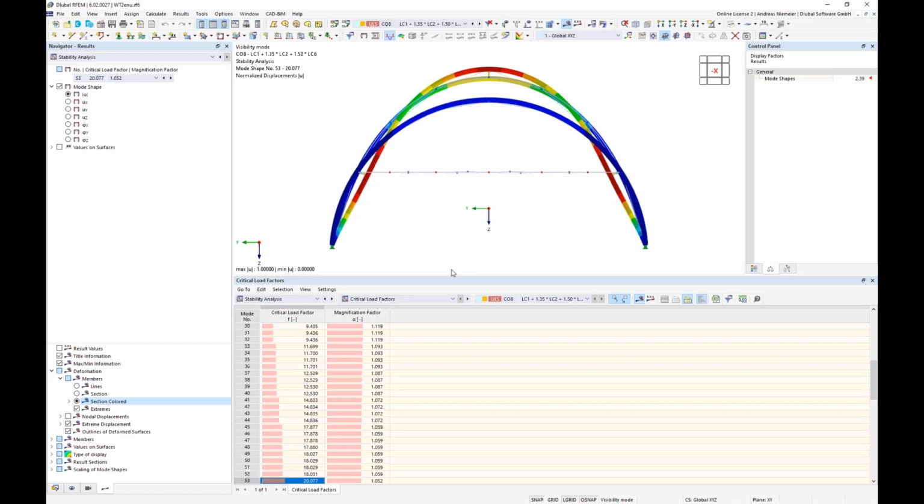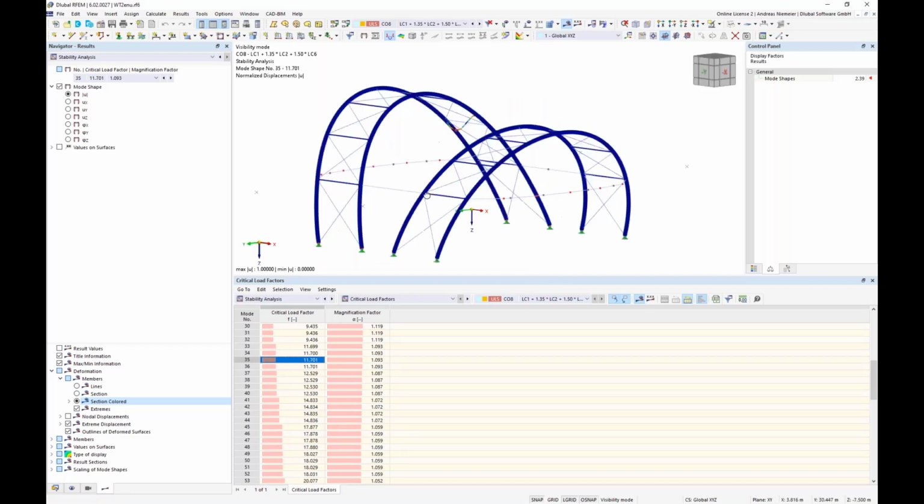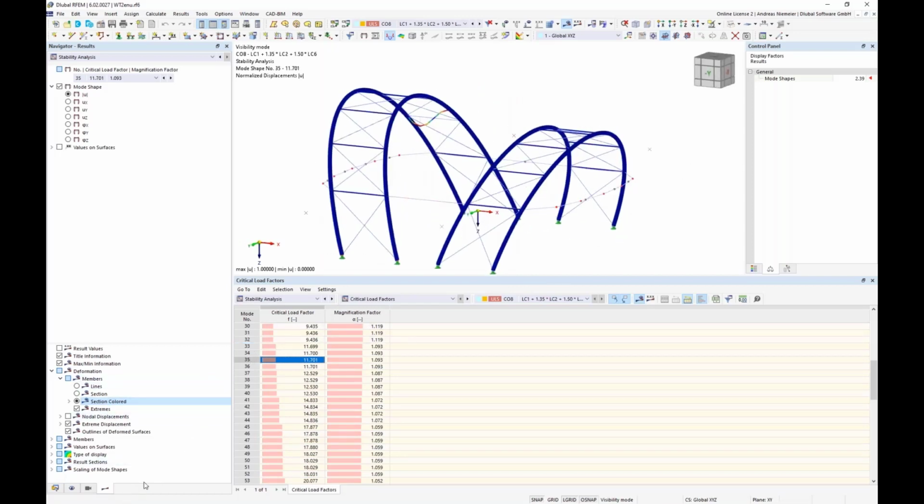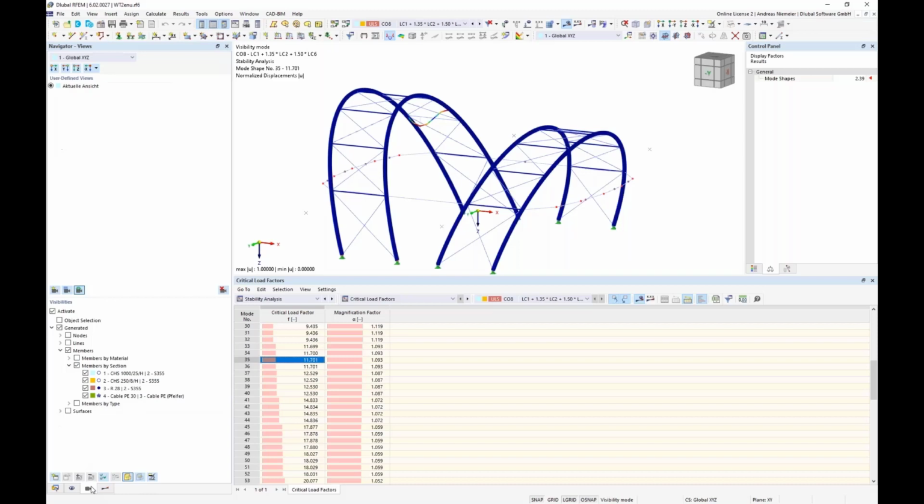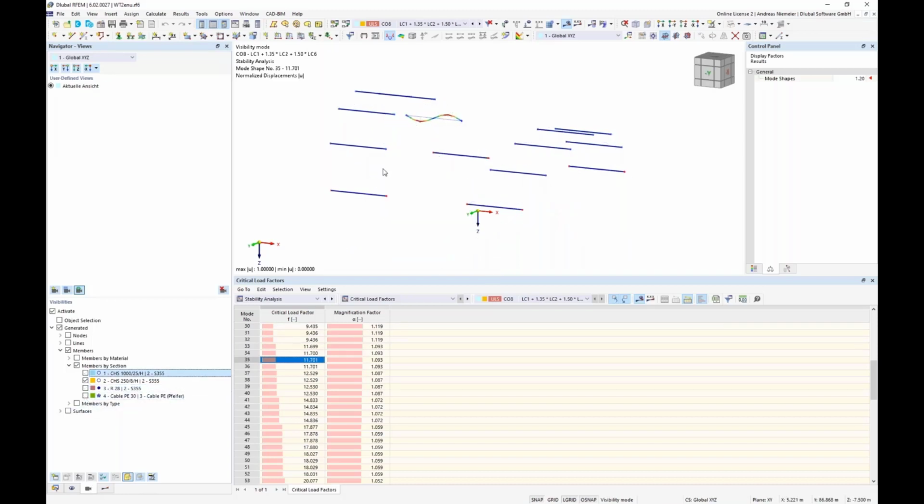And because it will not increase the results by more than 10%, I don't see it so critical, even knowing that we're already calculating geometrical nonlinear with wind loads. So I don't see this as a critical stability issue. The buckling of these truss beams is governing, but here I would say we have to design it with a buckling check.